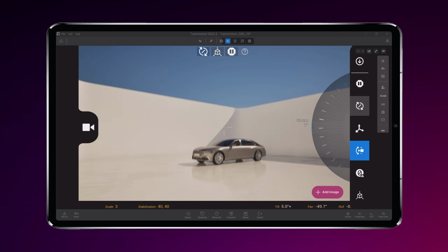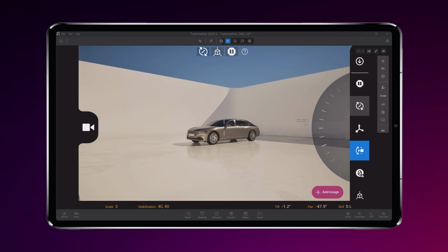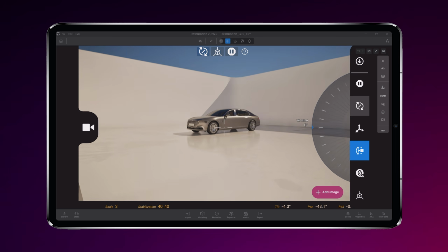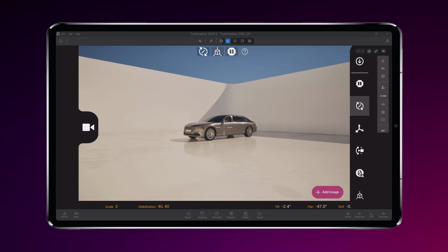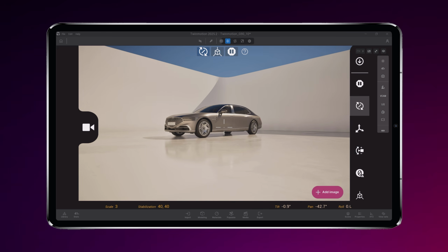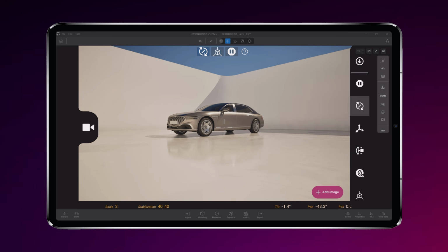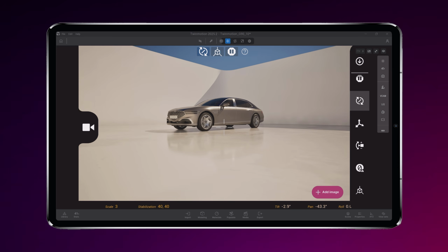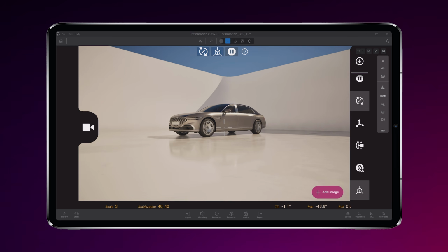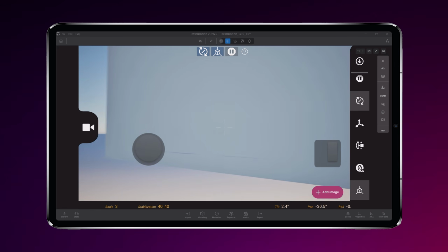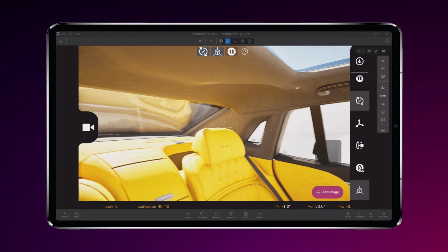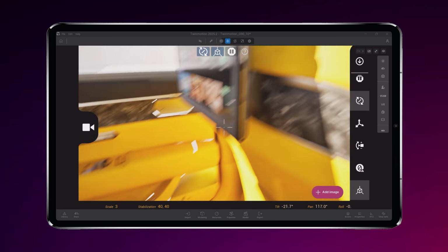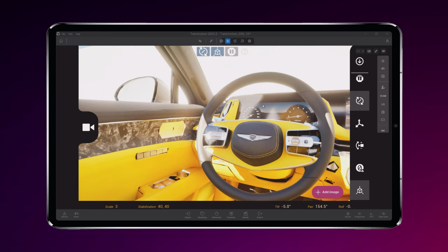Tilt offset is next, which applies an arbitrary offset to the tilt of the virtual camera, making it easier to hold the device when viewing your Twinmotion project at an angle. Next is the zero to parent icon, which reverts the virtual camera position to its original position when starting the VCAM app. Last but not least, we've got the local space flight mode. This makes the joystick movement follow the forward direction of the camera instead of the world, giving you some additional options for controlling your camera in the VCAM app.